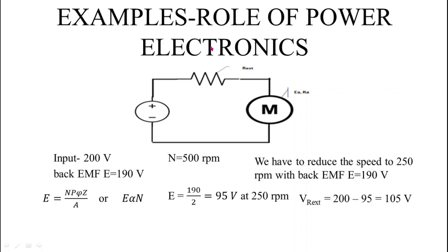I give you another example. In modern days, to regulate the speed of the fan in your home, a very small circular regulator is used. That is a triac based speed regulator. It is very small and efficient. But before that, large resistance based speed regulators were used. They were of large size because of more losses in them, due to which they have large heat sink requirements. That's why they were very large. So these two examples explain the role of power electronics.